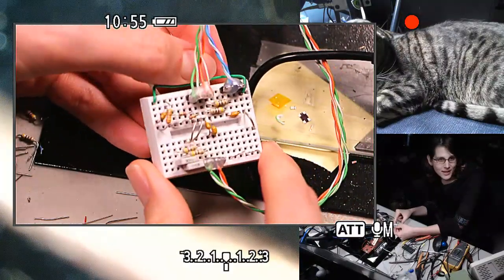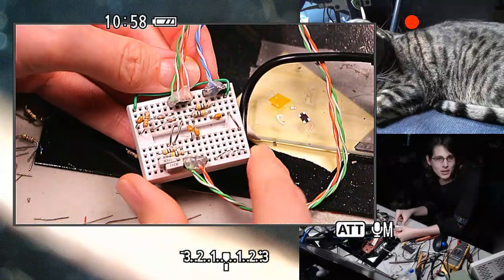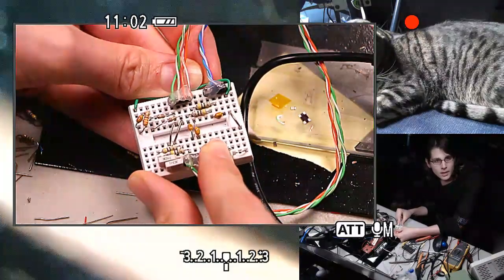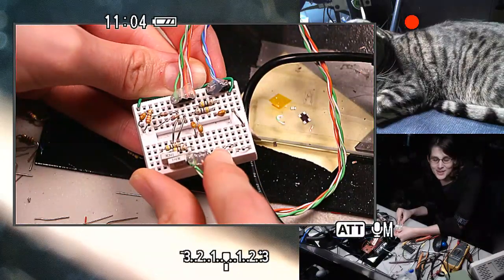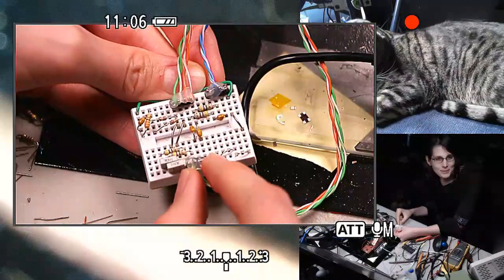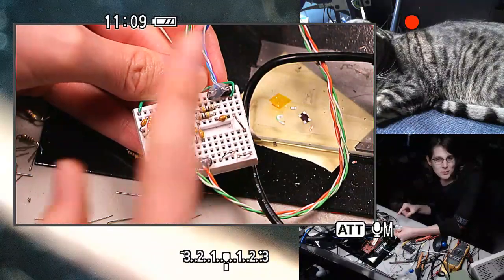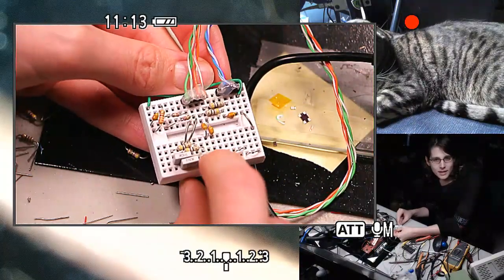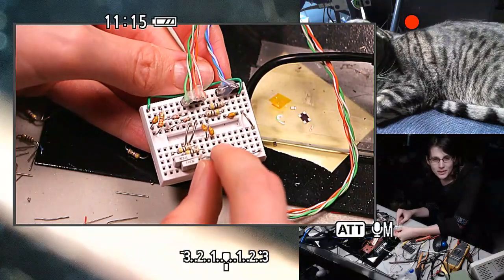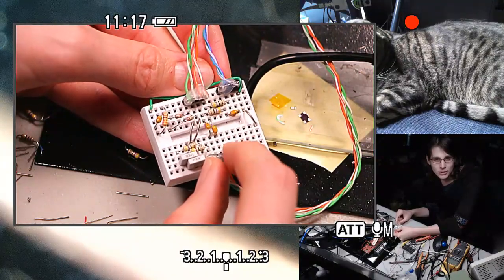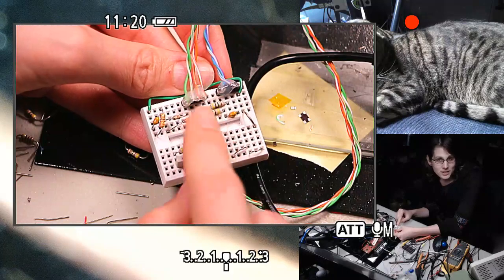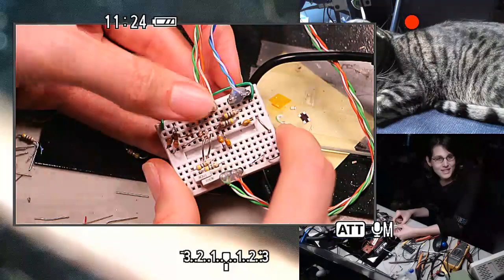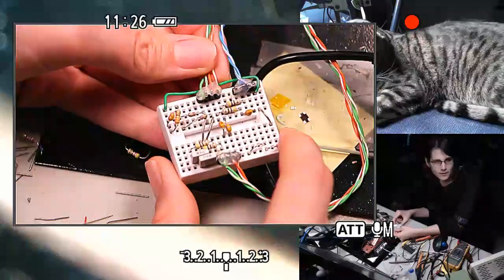So I don't know. One option is to go and try to understand more about how that ENC28J60 PHY works, but I was hitting some other problems too, which gave me pause about having this communication between two different kinds of Ethernet PHY, and it looks like they might be disagreeing on what the link integrity pulses should look like, and especially the ENC28J60 is giving me some really short and not very strong looking link integrity pulses when it's underclocked this far.